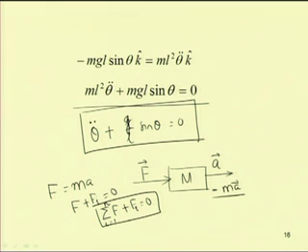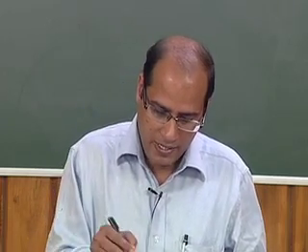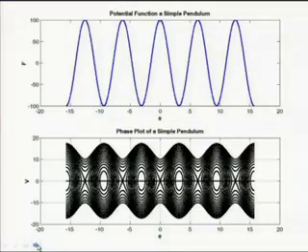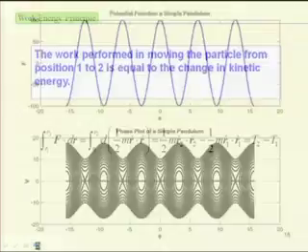The advantage is that in a static system we can apply the virtual work principle. By applying the virtual work principle, we can convert the vector based equation of motion to a scalar based equation of motion, using scalar quantities like the potential energy and kinetic energy of the system. Last class we also saw the qualitative analysis for finding the phase portrait of a simple pendulum.